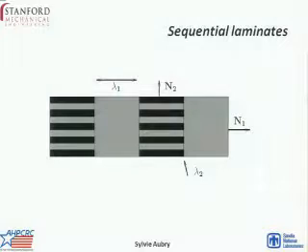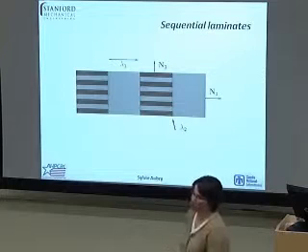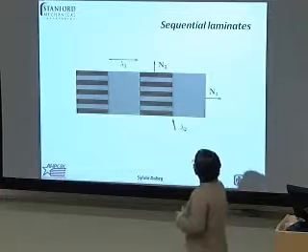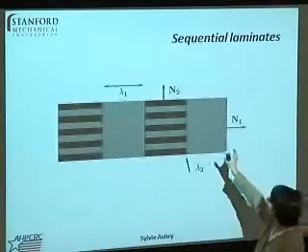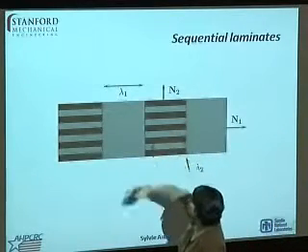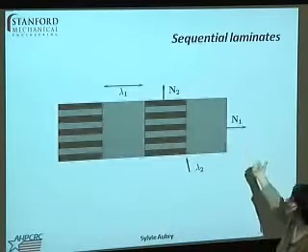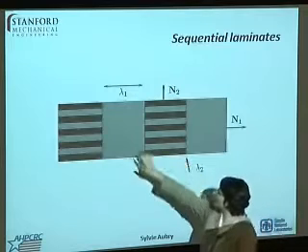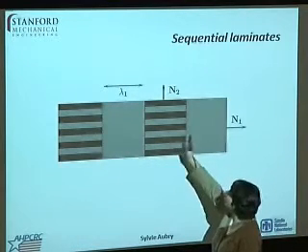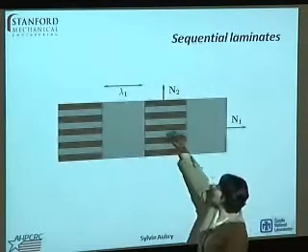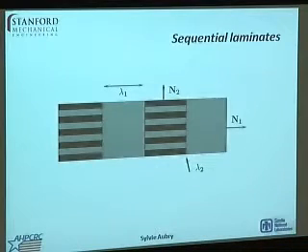So this is where we are saved in a way. There is a special microstructure that is called sequential laminates. And the way you construct such a microstructure is that you have gray, and let's say all black in a given direction. So that will be a laminate of rank 1. And then in the black area, you give yourself another direction and a given proportion, and you put black and white again. So this is how you calculate a sequential laminate.